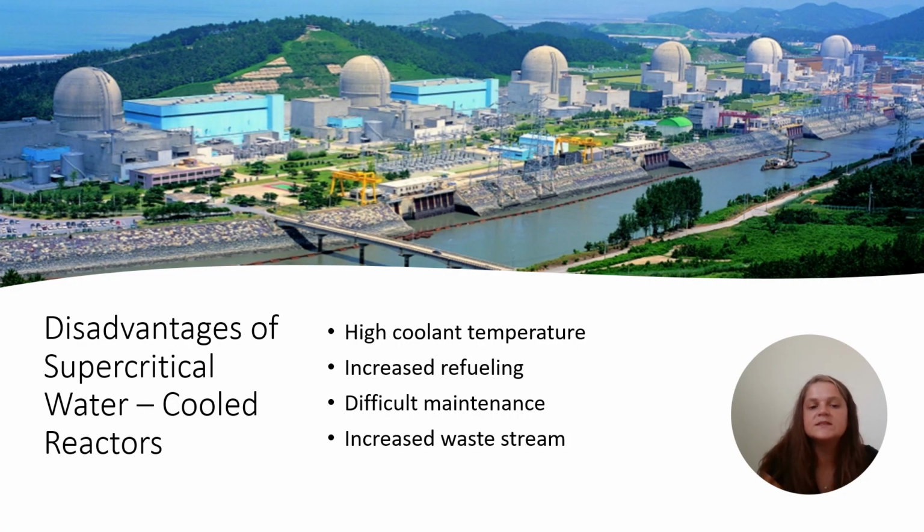And lastly, the disadvantages of supercritical water-cooled reactors. One of the disadvantages of a supercritical water-cooled reactor is its high coolant temperature. This leads to high cladding temperature, which requires the use of stainless steel and nickel-based alloys as fuel cladding materials. In addition, refueling frequency is increased compared to today's fleet of nuclear reactors.